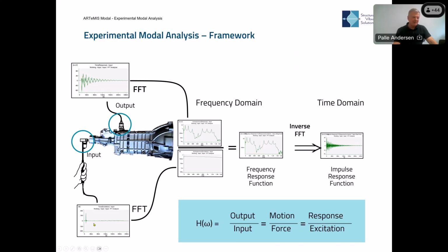So an impact like this is very nice, because in frequency domain it shows that we are exciting a broad band of frequencies. All the modes in this band are being excited very nicely and more or less with equal force. So this is a very nice way to have a spectrum for the input forces that we are using for experimental modal analysis. These two are divided with one another. There are different ways we can do that.